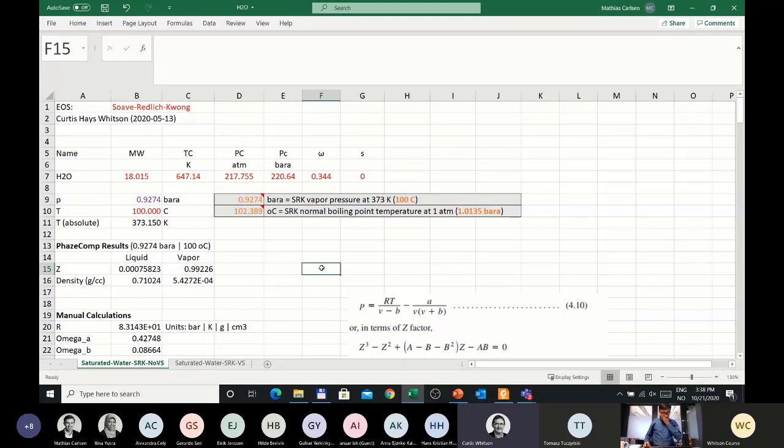Yeah, this shows the mechanics of how an equation of state can be used for a pure compound, or as you'll see later, it's the same exact equations if you have a mixture, and that mixture is single phase. You just calculate an average A, an average B, kind of a molar weighted average. And once you get the average A and average B for the phase, you can calculate its density as well. You can't do the equilibrium calculations in such a simple way, but just the volumetric part, you can do that way.